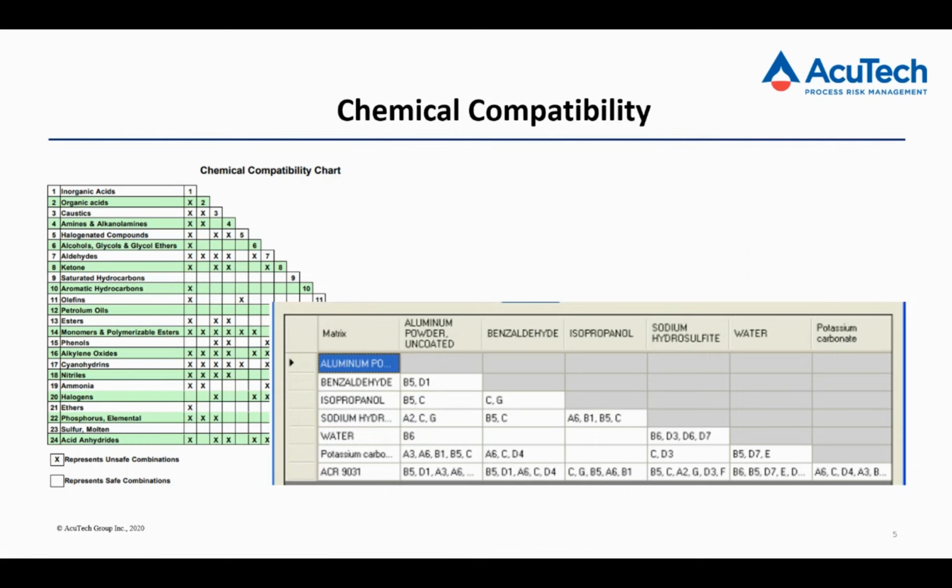Often if you have unique or newer types of chemicals, you can base your reactivity matrix on chemical composition or the active parts of the chemical molecule. You can also do reactivity testing if you've got something that's really unique or unusual. There are a number of commercial laboratories around the world that will take your products and run them through a battery of tests and help you figure out what's good and what's bad.